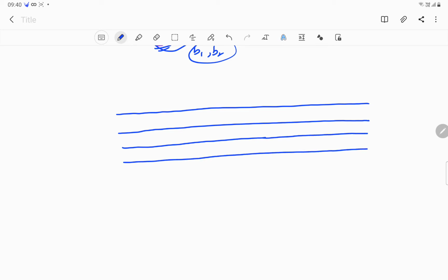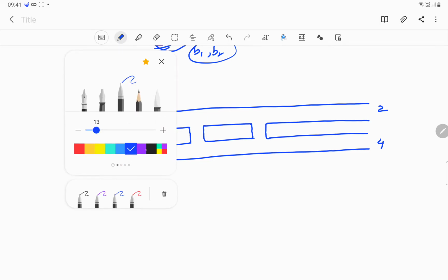So we have the waveguide 1, 2 as the primary waveguide, 3, 4 as the secondary waveguide. Then because it is a two-hole directional coupler, we need to have two holes in the primary waveguide and we need to create two holes in the secondary waveguide as well. So let me combine it. Let me join these pointers. So we have this as our waveguide. This is how it looks.